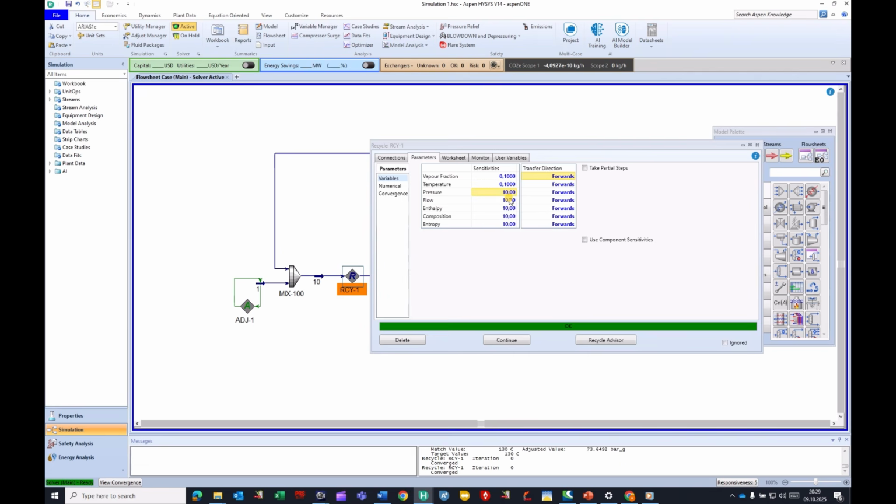Also remember, very low sensitivity values can make problems when you are converging your simulations, because it will go to endless calculations and might not find a solution with the given sensitivities. So you can start with the default values, and when you have completed your simulation, then you can refine your recycle operations one by one and check, and you can also use the recycle manager.